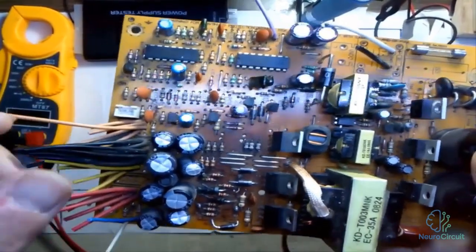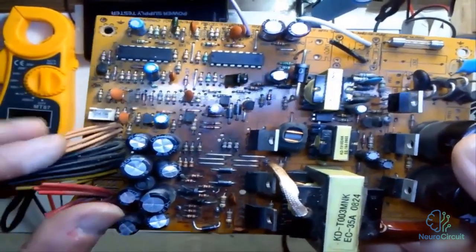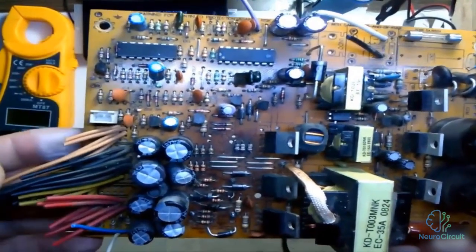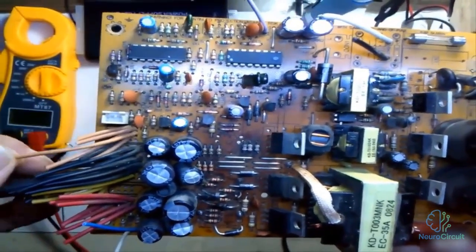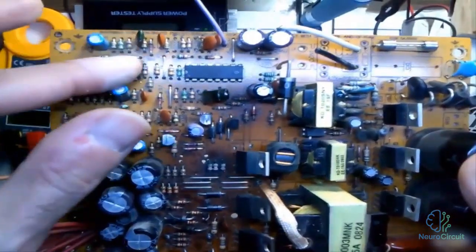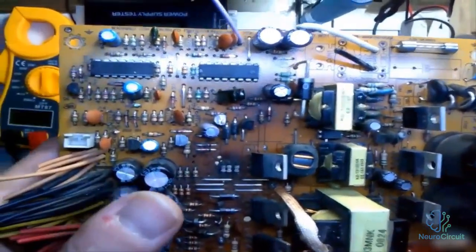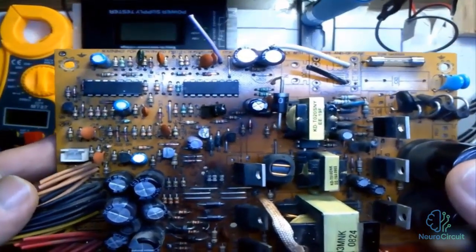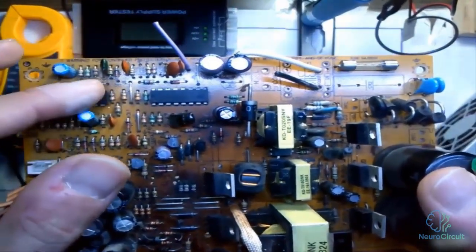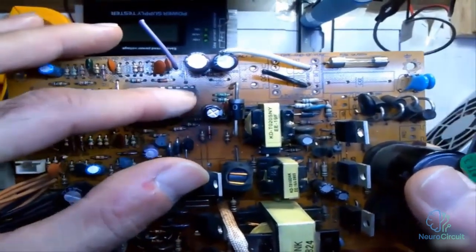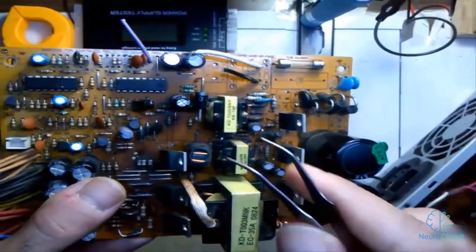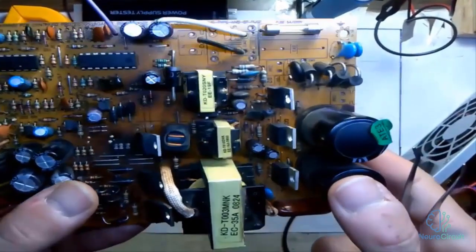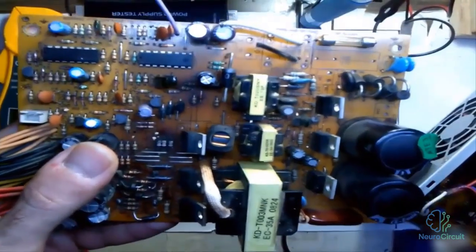The same goes for the positive 12 volt, the positive 5 volt, and all the voltages; their outputs should be normal. If any of these voltages have an output that's above or below a certain limit, the control circuit, which is managed by the IC and is located in this section, detects any abnormal or improper output and ultimately instructs the control circuit to shut down the power supply. The control circuit then completely shuts off the power supply, but this only happens if the power supply itself is actually healthy and functioning properly.